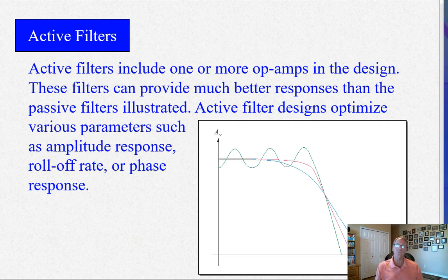However, when you put a filter in the circuit, what happens is that feedback becomes something special. It becomes something more than just the gain. In other words, those two resistors, the RF and R1 or RI, right? Those play a different role, or more role than just gain, okay? They do of course control gain, but they also control something called the damping factor, okay? And the damping factor, depending on how much gain you put in, will determine the filter characteristics of your active filter.